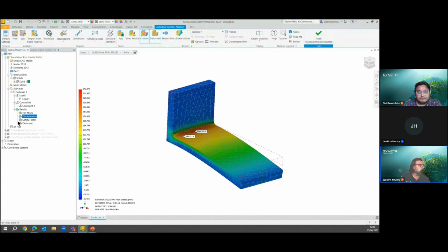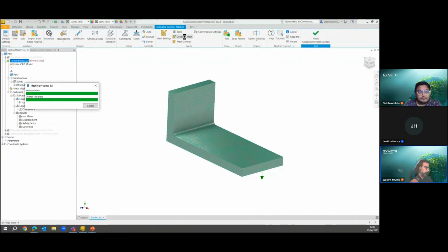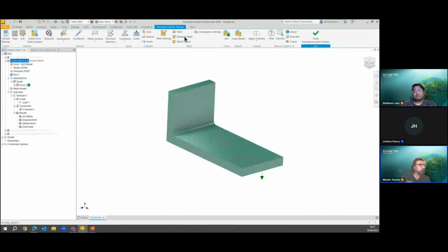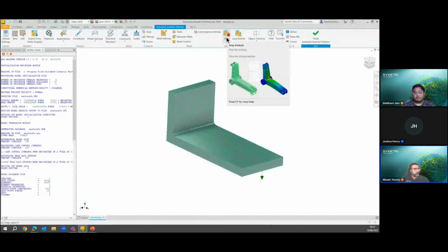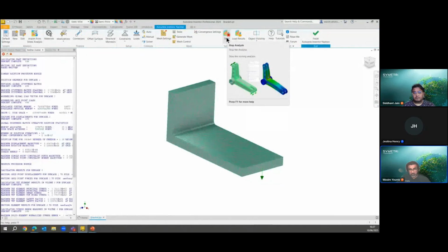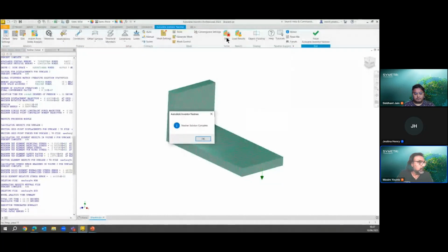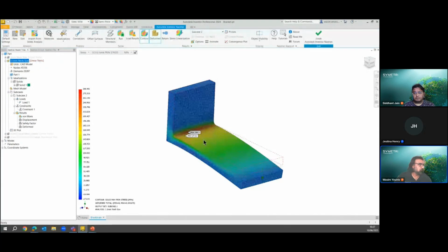We'll stick with that. And if I then go to my next study, generate the mesh again. I better make a note of this. 242 was it? And then we run this again. This is one of the reasons why I put a very simple example so we can run it live and you can see it. And I'm hoping it's within 10% of 242. And also, right, okay, we're getting there. Okay, 242, 288. So we're getting there, we're getting close.